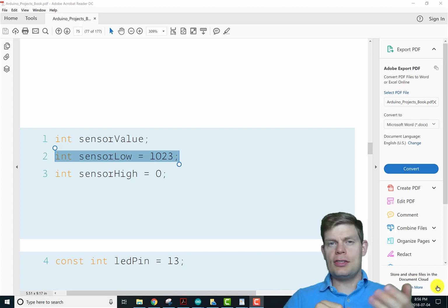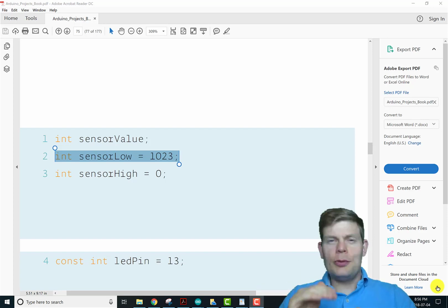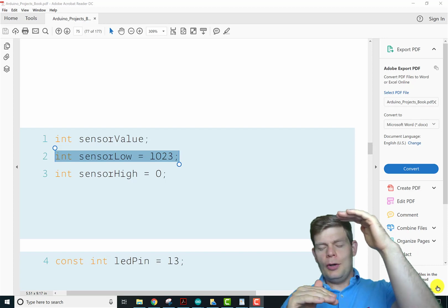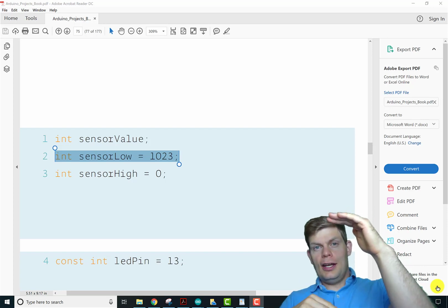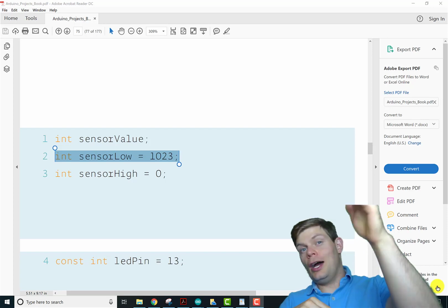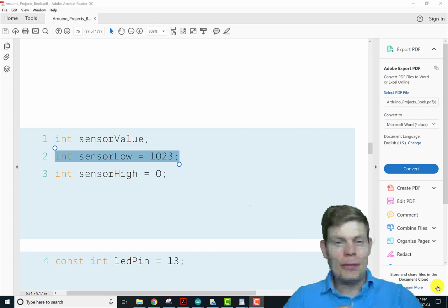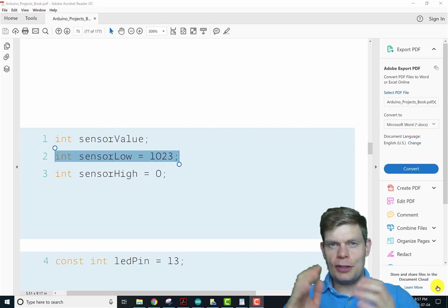So what this one does is it takes the first 5 seconds and looks for the lowest light value it sees, and the highest light value it sees. By knowing the minimum and the maximum, it can map the minimum value it actually saw in the first 5 seconds to the low end of human hearing, and the highest light value to the high range of human hearing. Then you're not always going ultrasonic or missing some of your range. It's just perfectly set up.